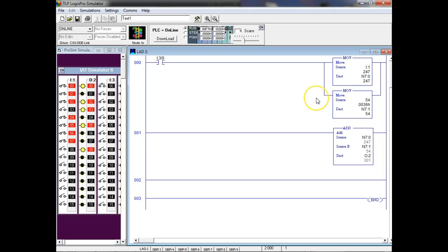So what we would do next is take the same two numbers and subtract them, then take the same two numbers and multiply them, then take the same two numbers and divide them. So you're going to draw your logic. You're going to put one rung to do each math operation. You're going to put a master start/stop on the thing. So all your diagrams have to have a master start/stop, right? Did I say that right?